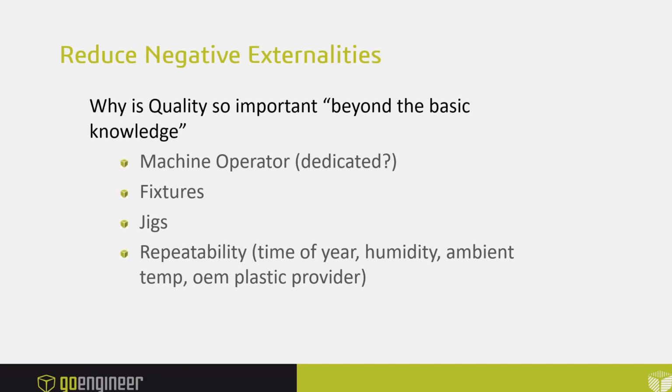Hey, the mold runs fine until it gets to 2 o'clock in the afternoon and it gets hot in California. Or it runs good until it's midsummer and the humidity is 110%, and there's just so much moisture in the air we can't keep the moisture out. All of these things are factors that we could mitigate, in addition to the quality, the weld lines, looking at the flow, selecting the right machine, and so on and so forth.